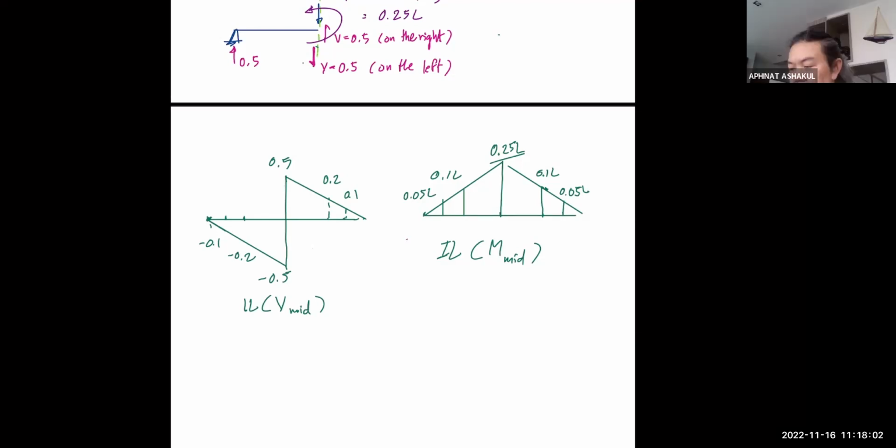Okay, so you can see, all right, that is the introduction of the influence line. You need to change your perspective a little bit because now it's the values of one design function at one location. This is no longer the value of the moment at each location.